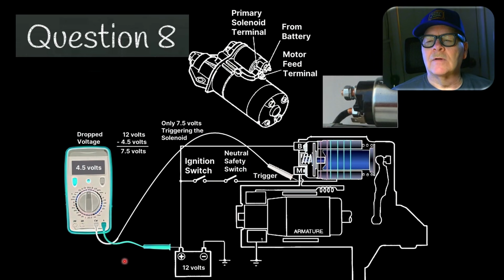All right, so let's say you got this one here, and this is the trigger terminal that's going to operate the solenoid, and you're dropping enough voltage that it doesn't slap this contactor in. It's supposed to slap it in really hard. You know what a contactor does, like on a hybrid or an electric vehicle or an air conditioning unit. A contactor is basically a big copper contact that's going to suddenly slam against two posts.